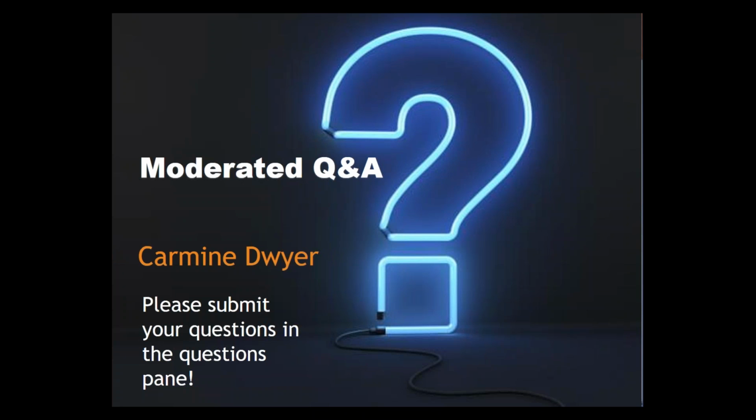That is certainly an option, although using recessing for transverse markings and for letters and symbols, I would like to see a little bit more evaluation of that before I would make the recommendation that yes, all those markings should be recessed. Like I said, thermo is definitely an option, but one thing you want to consider with thermoplastic is it is a very thick material.